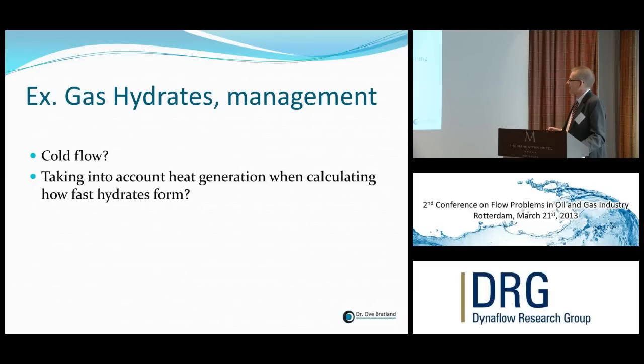One thing that is not normally done in calculation of potential hydrate problems nowadays is that you do not take into account the heat generated by the hydrate itself. The most traditional way is to make sure our temperature doesn't fall down to the temperature where we get hydrates. Now, it just so happens that when we come down to that temperature and hydrates start to form, the hydrate formation itself releases energy.